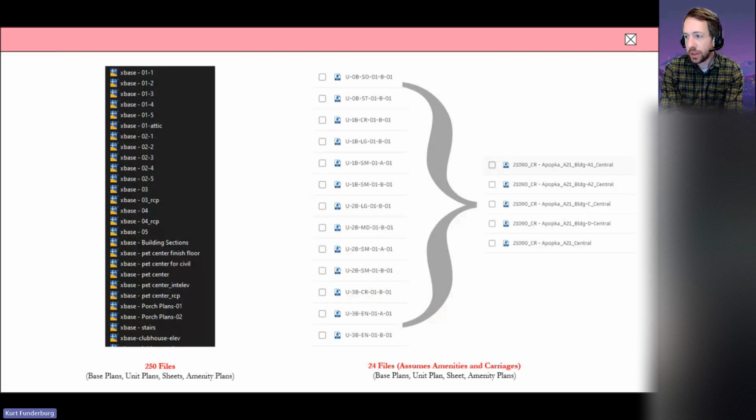And so this was a graphic that Elliot had made, where we're talking about where we've come from and how difficult it is to manage a CAD project at the scale of a River Lights or a Leo project. We have the ability to go from hundreds of files to, hey, we have 20 units or less than that, to a handful of buildings, to one site file, and then we print from that one site file. If we manage it correctly, it's a whole lot less trouble to manage all these files if we understand how it's structured.